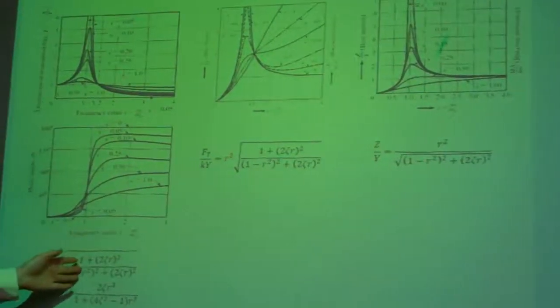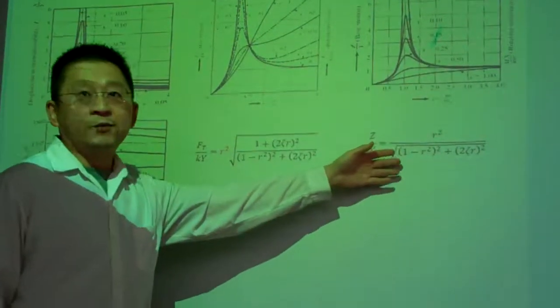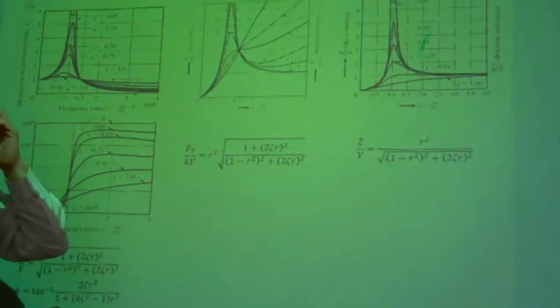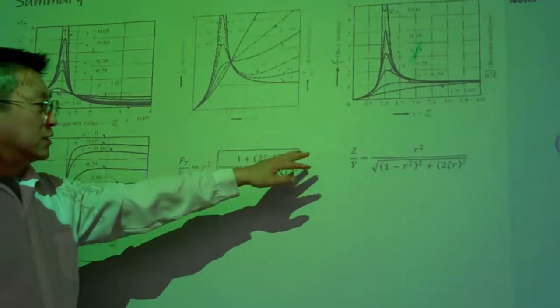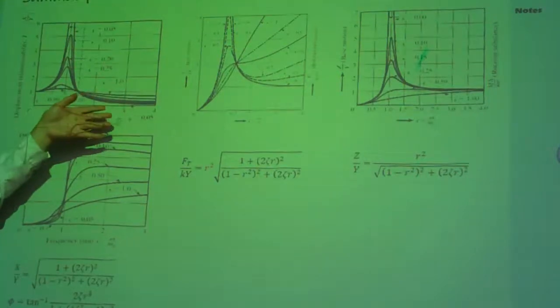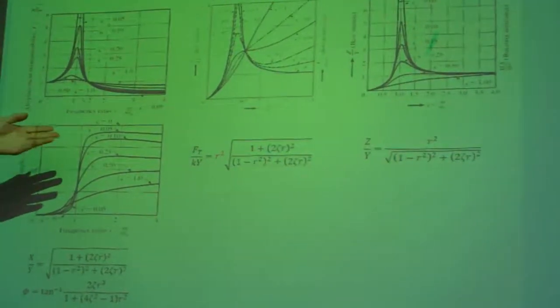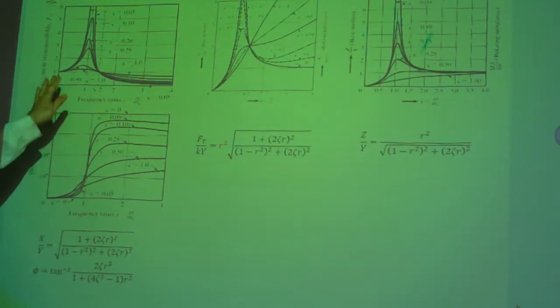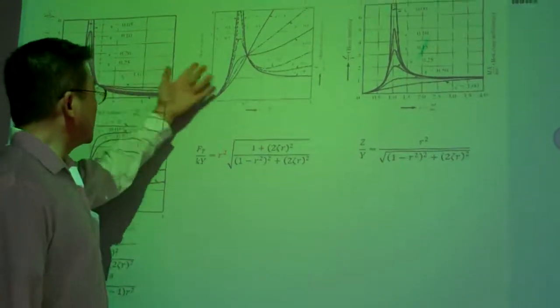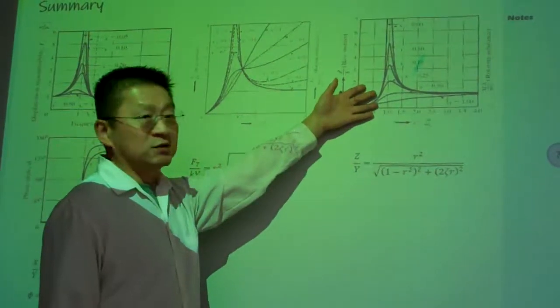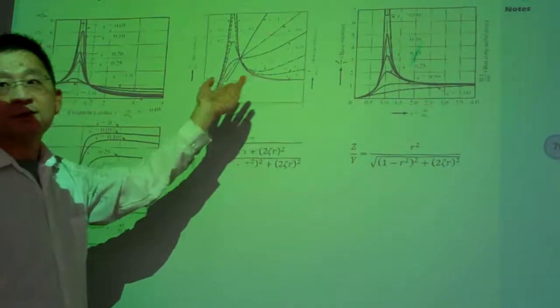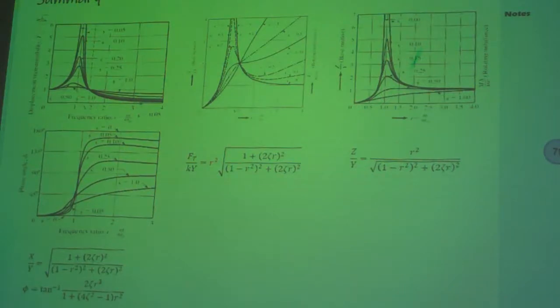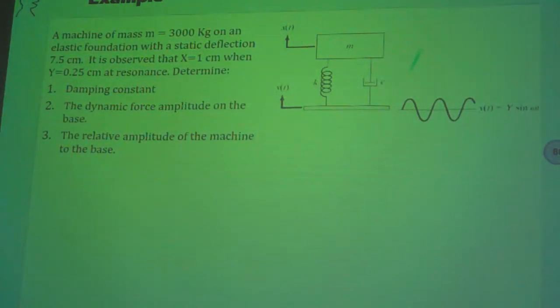So you can see three different categories based upon the base excitation, and they have different forms. I would say this page will be more useful for our calculations, so I summarized it here. If you look at this carefully, the transmissibility curves are different. Pay a little bit of attention to the details here. Okay, and here we can look at one example.